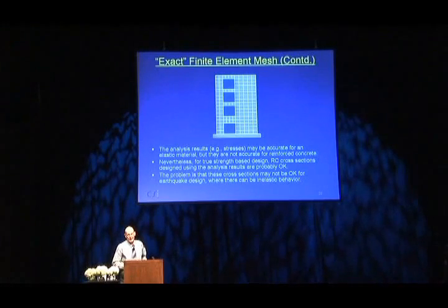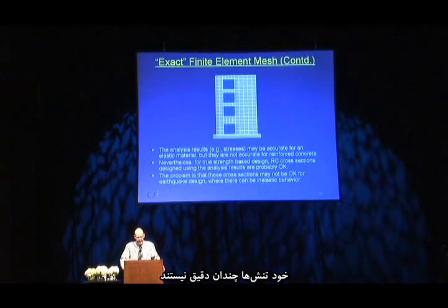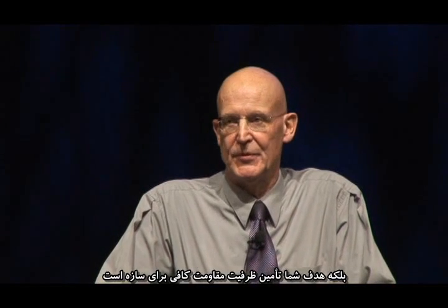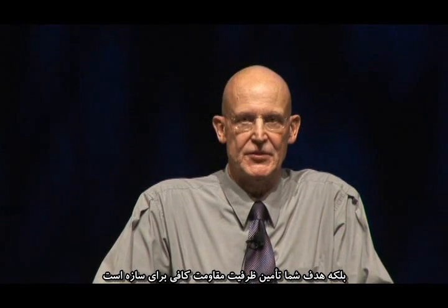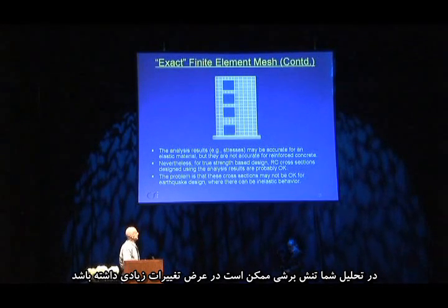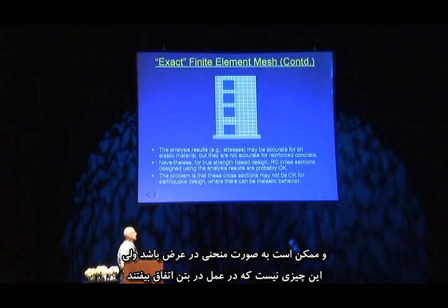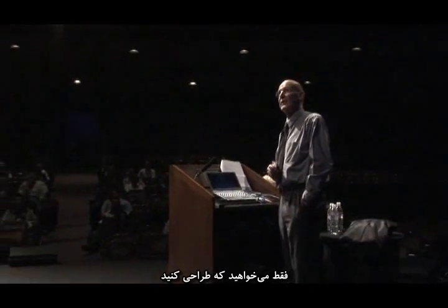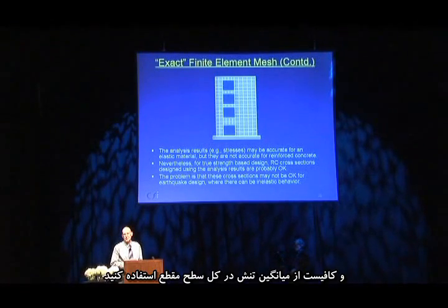And that's okay. The stresses themselves are terribly inaccurate, but the axial force, moment, and shear force you calculate are plenty accurate enough for doing a reinforced concrete design. Your purpose wasn't to get an accurate analysis. Your purpose was to provide sufficient strength capacity in the structure, and you can do that from an elastic analysis. The shear stresses may vary in your analysis dramatically across the width, and they may be parabolic over the width. But that's not what really happens in concrete. In any case, you're not going to design each individual element with a different amount of shear reinforcement. You're going to have some shear reinforcement and just use the average shear stress over the cross section.